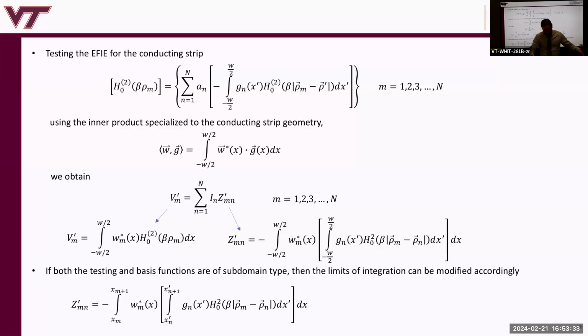If you have an antenna or a scatterer or a metasurface which is 10 lambda by 10 lambda, and the unit cells are lambda by 10, then you have 100 by 100 unit cells, which is 10,000. And then each of those has an anisotropic impedance tensor in it, which has 6 minimum degrees of freedom, right? So that's 60,000 unknowns. And if you want to do some kind of optimization on that, then you have to somehow do an inverse design of a metasurface that has 60,000 degrees of freedom. But you can do that. In fact, that's a lot of what I have done for my research.